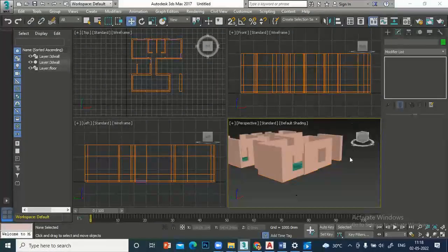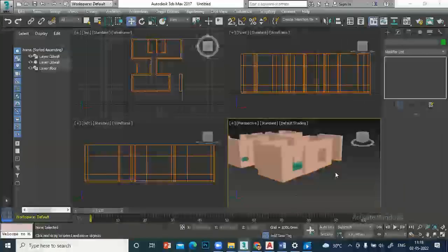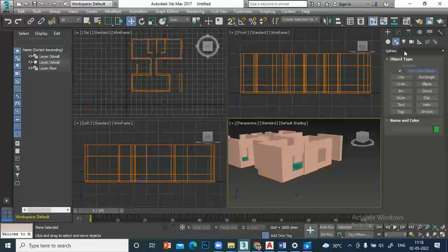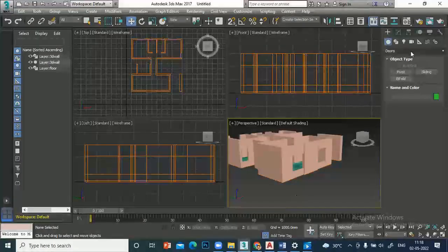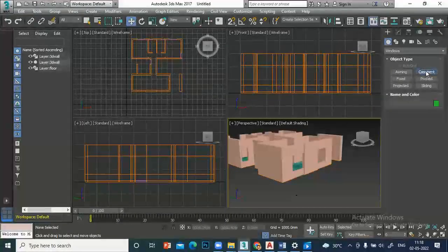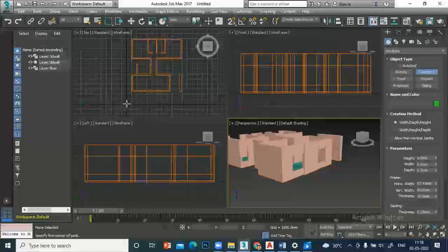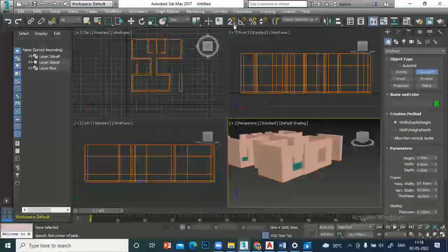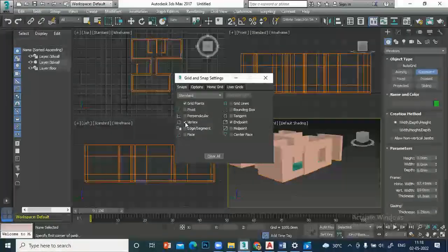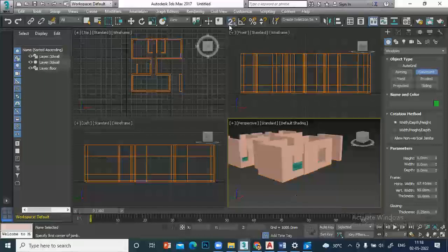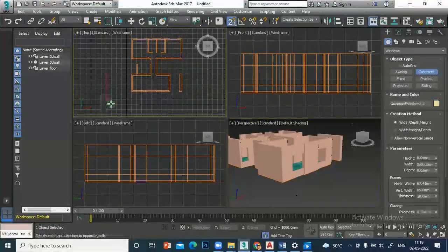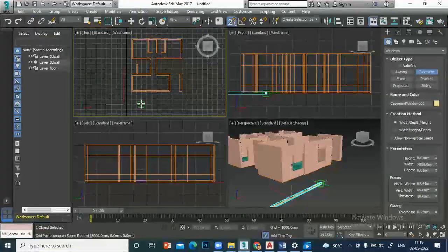Okay, now let me show you how to create doors and windows. We'll go to create, and first we'll do the windows and select the casement windows. Since I want to have a straight line here, I will switch on the grid. Right click here, so grid is on. Make a grid 2.5 on. Casement window is on. Click here, drag, put.